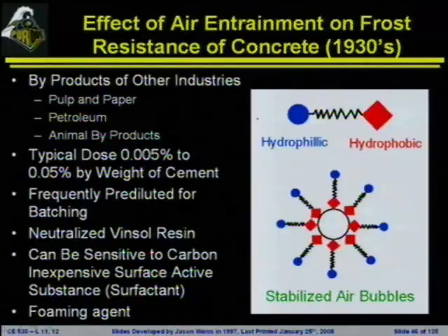Right, the basic way that these air entrainers are made, they are a chemical that will be inside the system. They're a chain, and one end of the chain will be hydrophilic, one will be hydrophobic. For those of you who may not remember what that means, hydrophobic is afraid of water, scared of water, much like my dog. Hydrophilic is much like my dog in a swimming pool. He hates the bath, that's the hydrophobic side of him, but he loves to be swimming in a swimming pool or a lake or a pond or a big puddle or whatever else is out there. Okay, one end hates water, the hydrophobic end, and the hydrophilic end really likes water.